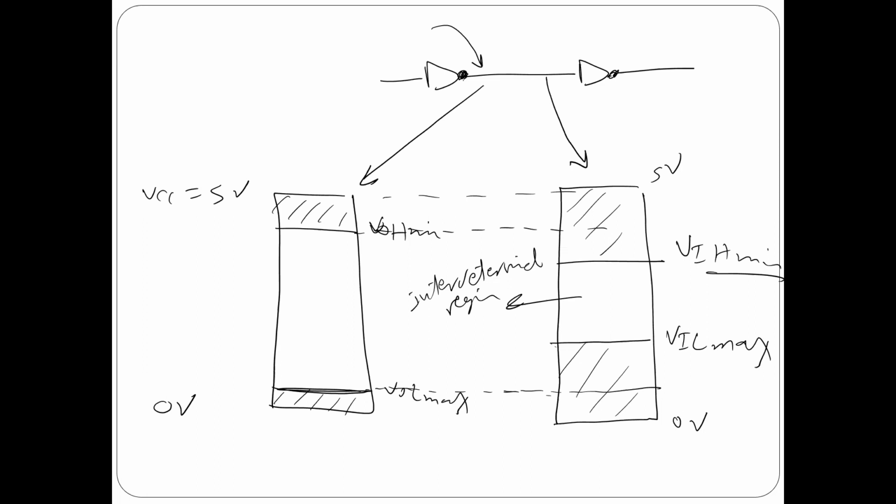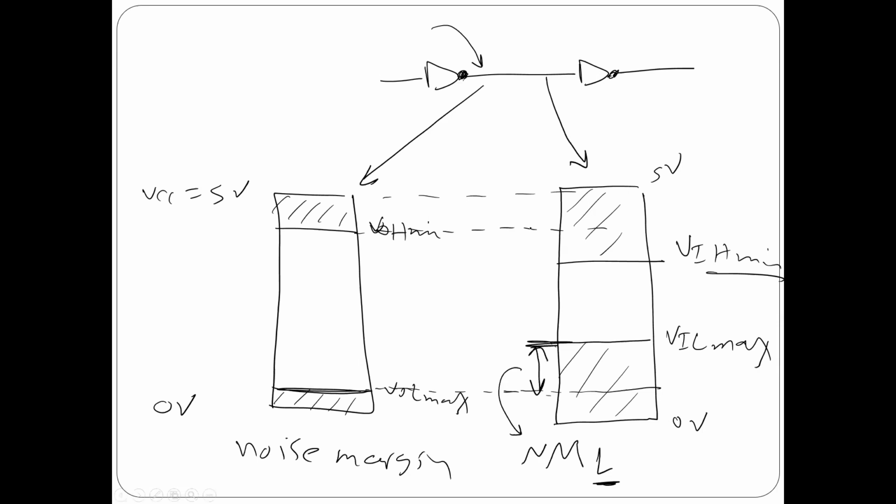There is something, I think in lab number 2, that you need to measure, we call it noise margin. This part here, from here to here, we call the noise margin in case of low, in case of 0. And this part from here to here, that's what we call the noise margin in case of high. I'm going to make it easy and tell you the idea.